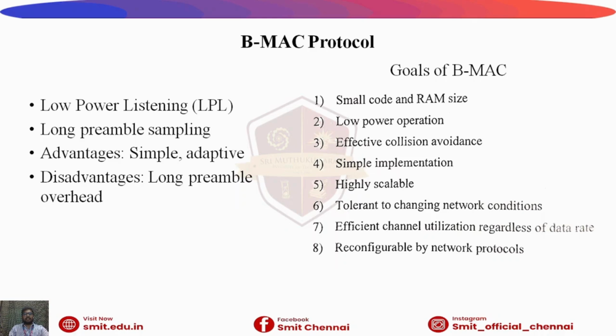Disadvantages are that the long preamble causes energy overhead and it is inefficient when traffic is high. The main goals of BMAC are simplicity, energy efficiency through low power listening, and adaptability to different traffic conditions. BMAC avoids strict synchronization, making it suitable for dynamic sensor networks.